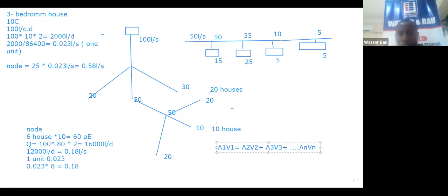So when I got 0.58 here, and I'm doing for node 6, it automatically becomes its own value plus the value downstream. And that is why in my Excel sheet, node 6 becomes this. Look at my address bar, 0.18, which is its own demand plus the demand downstream.